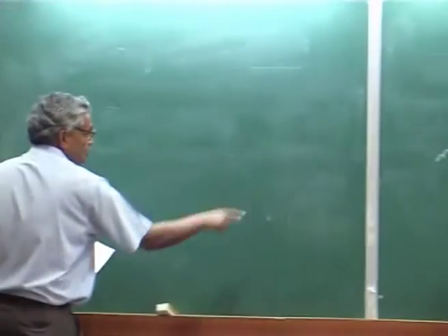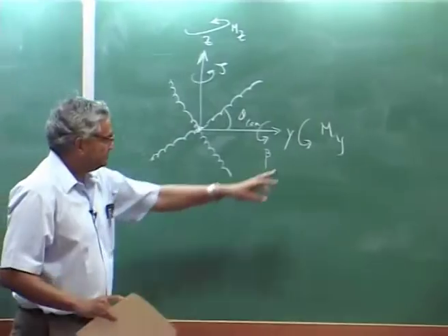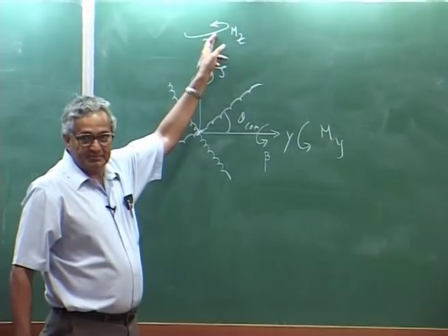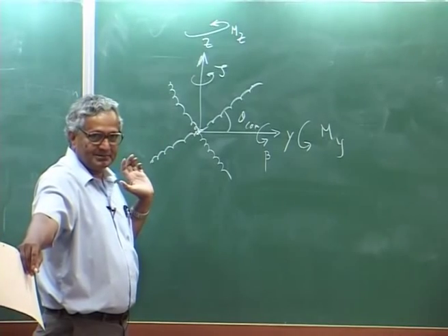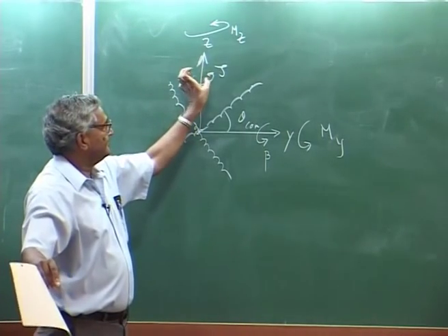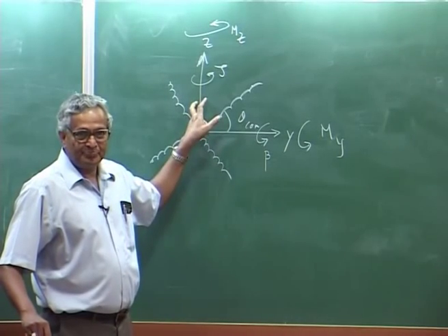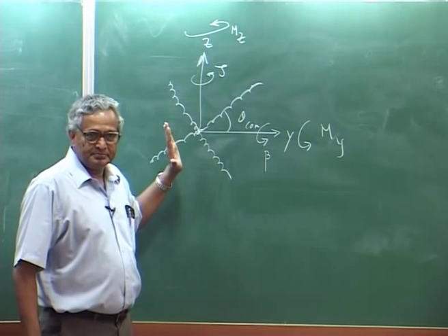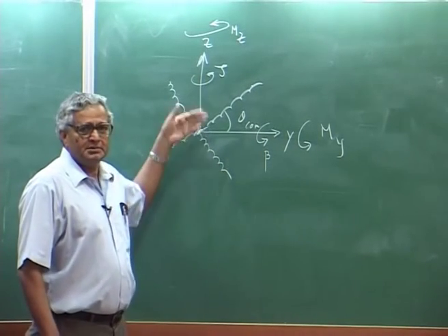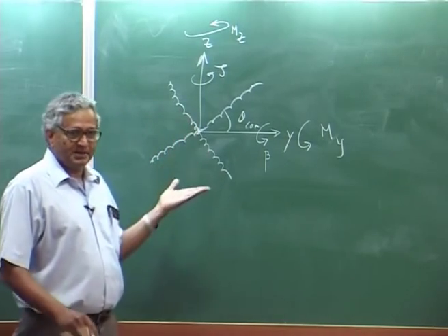So, I am just using this convention, applied moment My Mz. Because of that, the blade is down and it is rotating. So, both flap, lag. This is purely structural coupling, because my pitch bearing is inboard of the spring assembly.